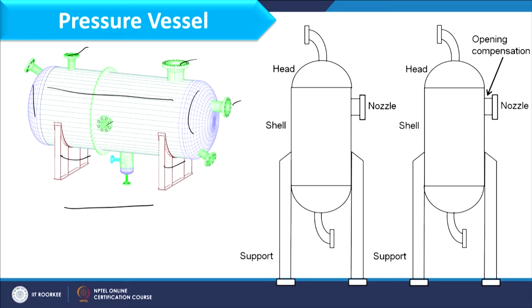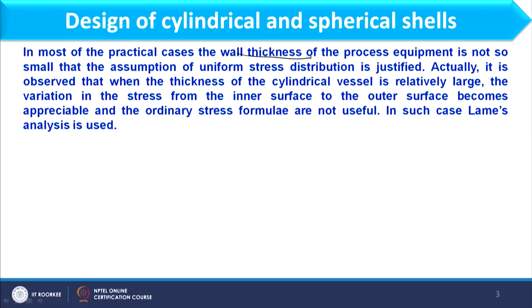So first of all let us start discussion on design of shell, and as far as design of shell is concerned, we will start with design of cylindrical as well as spherical shells. So in most of the practical cases, you must have the idea that what we are going to compute in designing is the thickness of different components. So here we will speak about design of wall thickness of shell.